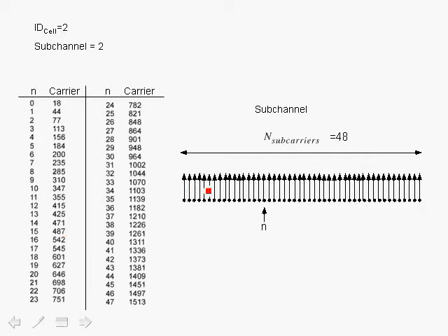And as we go and look at all the 48 carriers in this table here, we see that we achieve our goal of permuted carriers, and a single carrier is allocated for a particular subchannel. That is, a carrier cannot occupy multiple subchannels. So this table is very important. It shows that we have achieved our goal of permuting the carriers.